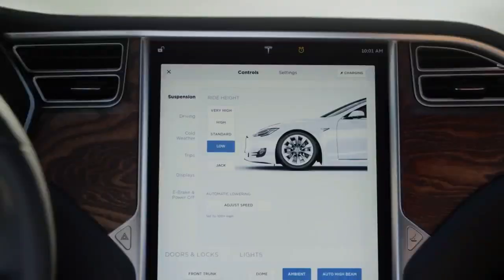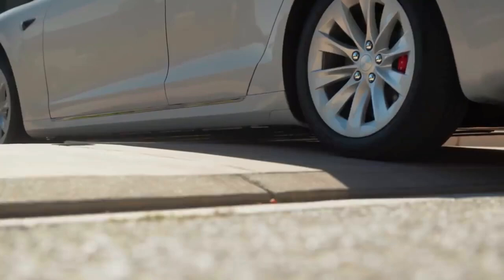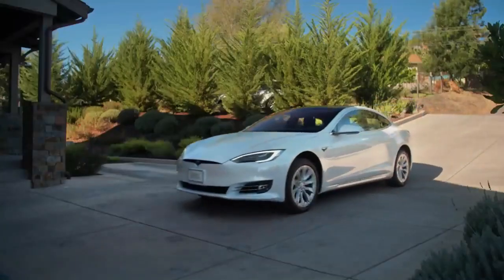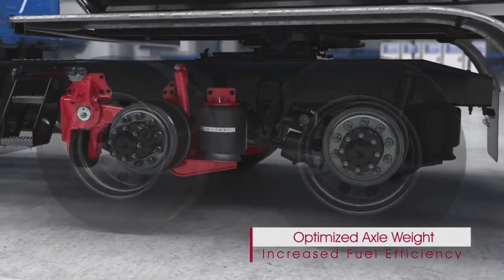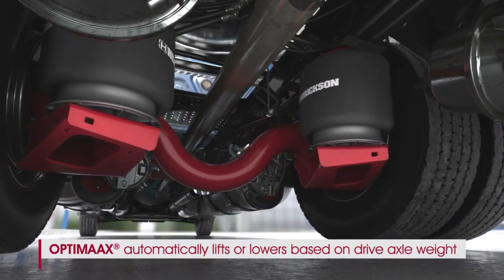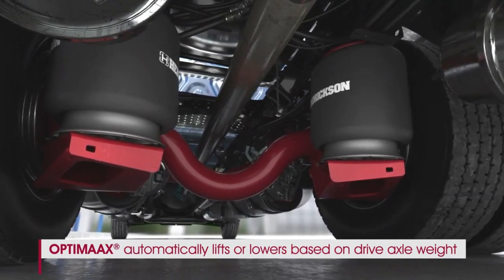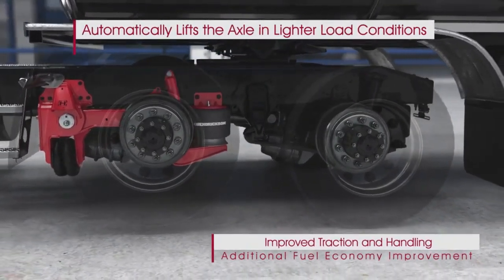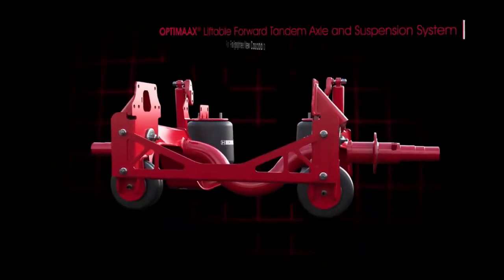Air suspension system definition. An air suspension system can be described as a suspension system that harnesses the qualities of air contained within a reinforced rubber column, often referred to as a bellows, to provide cushioning for the vehicle. These bellows are engineered to endure high-pressure air and undergo inflation and deflation as air is introduced or released, respectively. Unlike conventional metal springs, these bellows are employed to absorb shocks in the suspension system. To adapt to varying vehicle load conditions, air suspension systems incorporate height control valves that gauge the necessary amount of air to be supplied to the bellows.